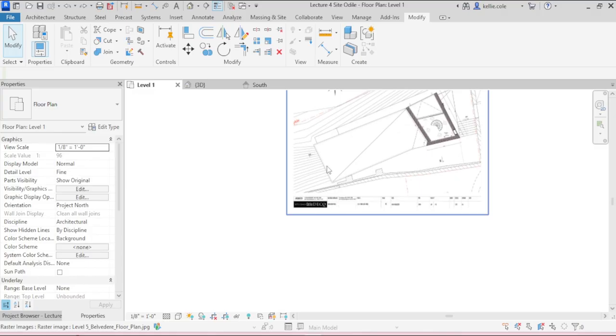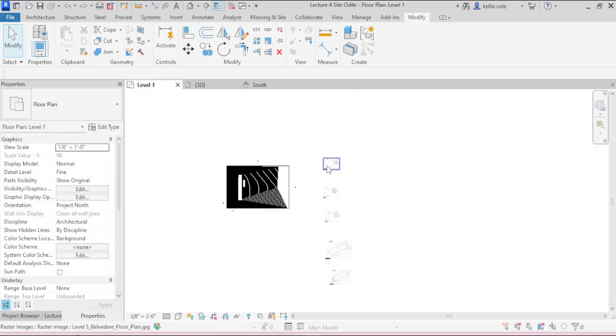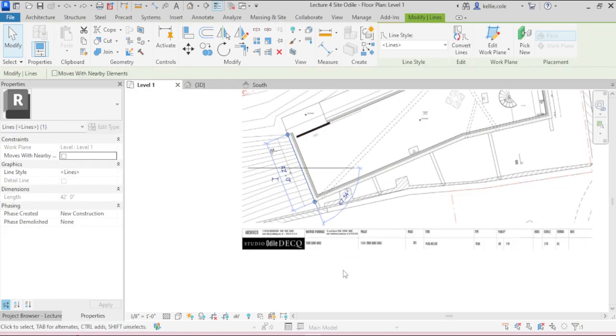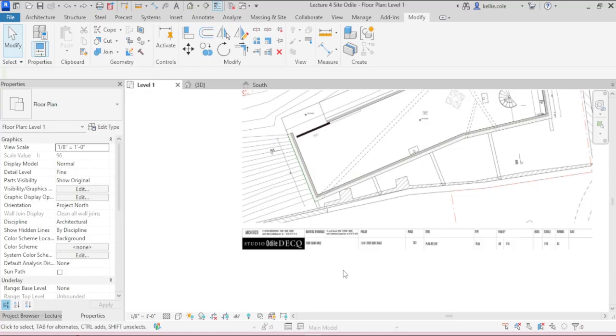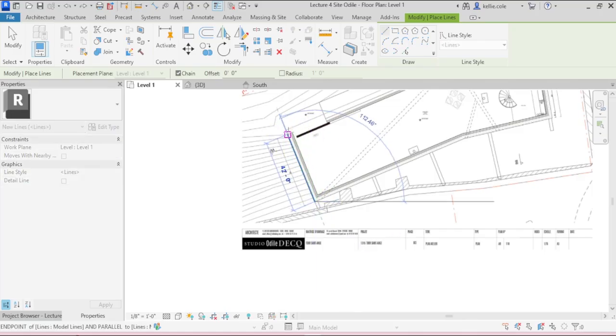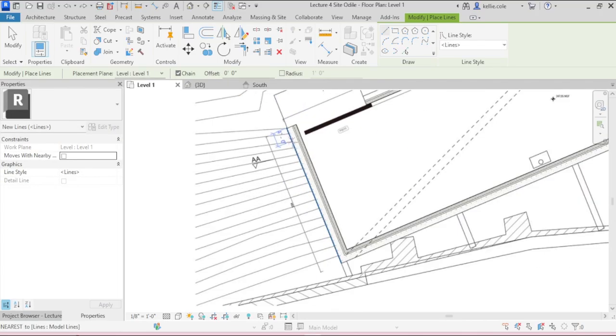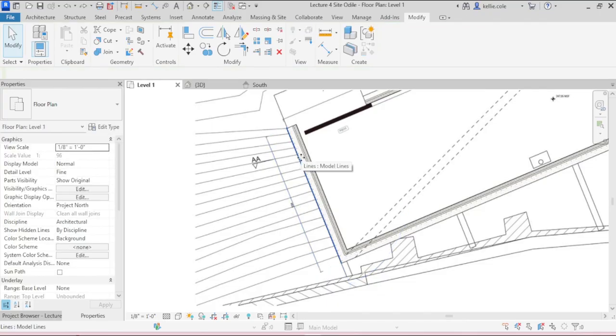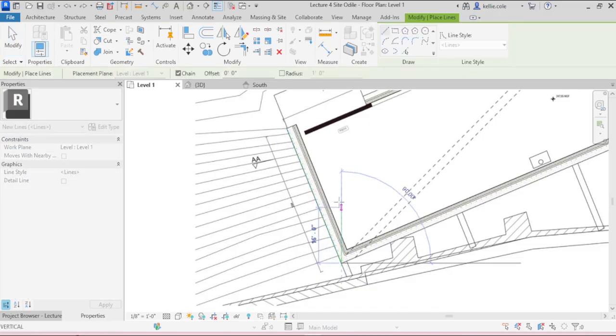That should be 23 feet. So for each image, I am going to draw LI for a line along that left edge. For me, the line length is 42, meaning it's too long. I need to draw a second line, LI, at 23 feet.